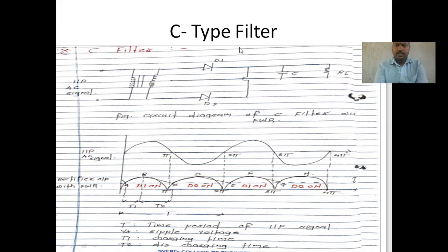So, we have seen that during the first positive cycle, plus and minus voltages appear across your diodes D1 and D2. During this first positive cycle, positive voltage appears across your capacitor. We know another function of a capacitor is that when a positive voltage is applied, it gets charged, fully charged, during this first positive half cycle. Here it starts charging.